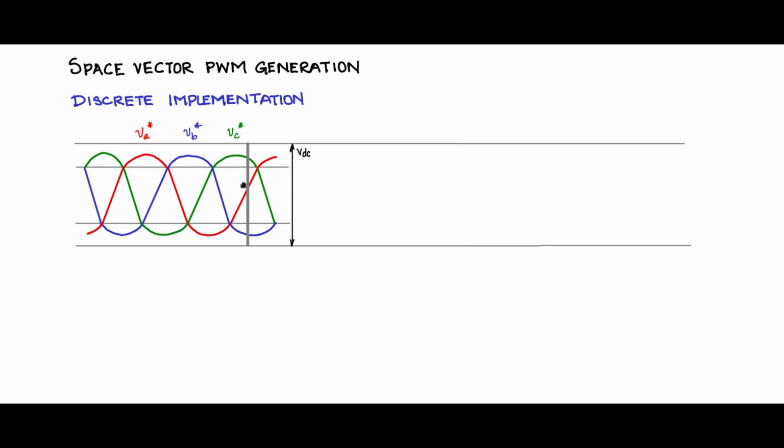Now, the carrier signal is there in this one. So there is a triangle. The three-phase AC signals are at 50 Hz, and lower frequency if it is a motor drive, but if it is for grid-connected inverters, this is fixed at 50 Hz. It will be more or less at 50 Hz. But you could use the same space vector PWM generation that we are discussing even for motor drives, where it could have a varying frequency. But for now, consider that this is the grid frequency.